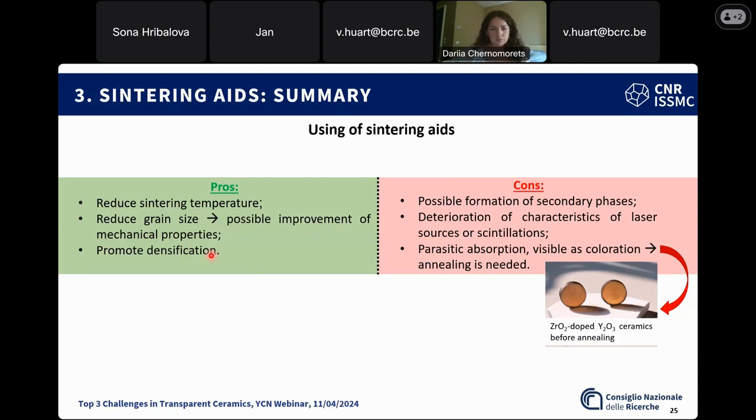So even if you have a cubic yttrium aluminum garnet, under certain conditions, it can start to become slightly birefringent. Then maybe it's not scattering at grain boundaries, but the grain boundaries matter because they define the grains that, when they're birefringent, behave differently. So in principle, no. Under some occasions, yes.